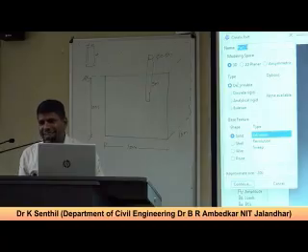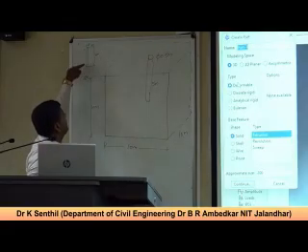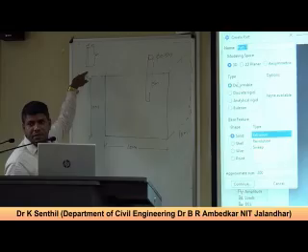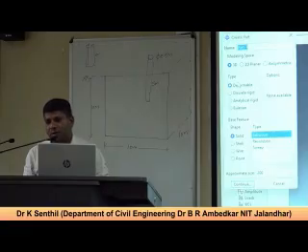Yes. No. In that case you can define the boundary conditions, and maybe here it's purely zero depth. Because you have the soil that is trying to flow around the pile when you apply the lateral load. So the best you can probably do is to take an axis of symmetry through the middle of the pile. Yes. But even then, the other direction becomes a problem. That's why people think. Okay.